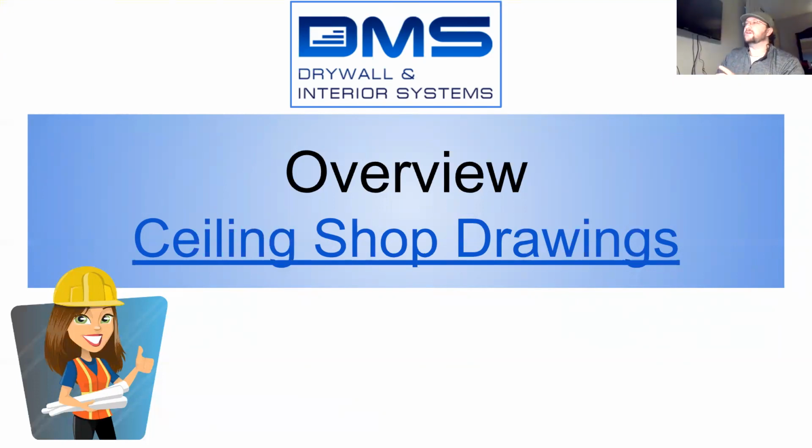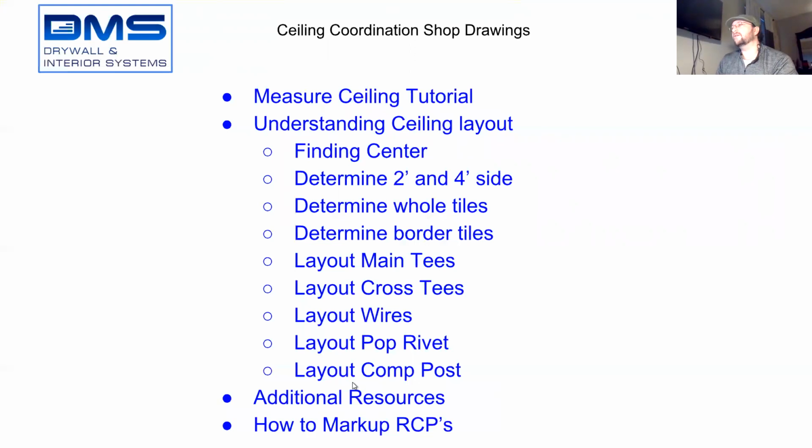Okay, so to get started, these are the items that we're going to cover in our slides, or in our tutorial today. We're going to cover how to measure ceilings, a tutorial on how to do measuring inside Bluebeam for ceilings. Then we'll do another section, ceiling layout: finding the center, determining which side is going to be the 2-foot side and which side is going to be the 4-foot side. We've got to determine how many whole tiles fit inside the ceiling and how many border tiles fit inside the ceiling.